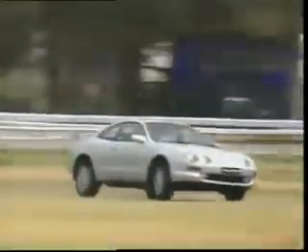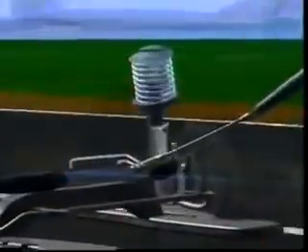The kind of independent suspension used on the rear of a vehicle depends in part on whether it's front-wheel drive or rear-wheel drive. If it is front-wheel drive, it may use a McPherson strut system at the rear, similar to the front suspension system. There is normally no steering on the rear wheels, so there is no need for the bearing in the upper mounting.